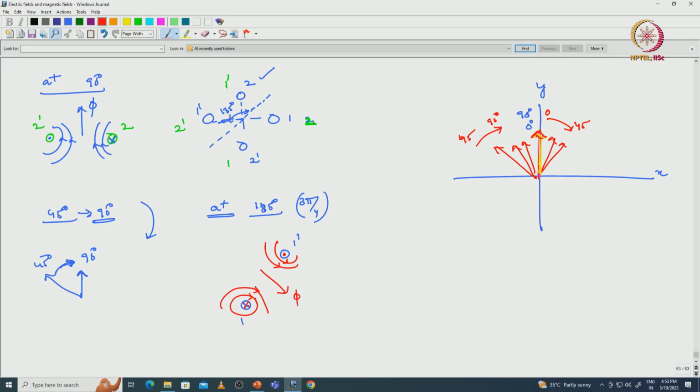So if we are rotating in a clockwise direction, but the resultant field is coming in an opposite direction, that means the rotor will rotate in an opposite manner. Earlier at 90 degrees, the flux vector was at this particular location, and it is now rotating in an opposite manner. So it is not a valid situation. To avoid this, or to make the symmetrical rotation, we have to reverse the current direction here: instead of dot, cross, and here dot is there.